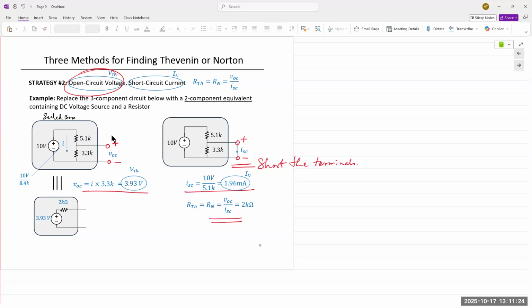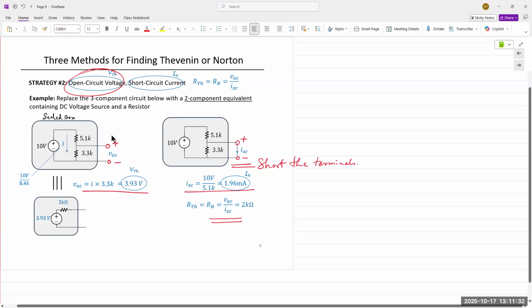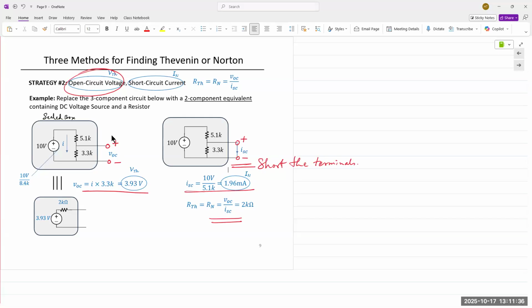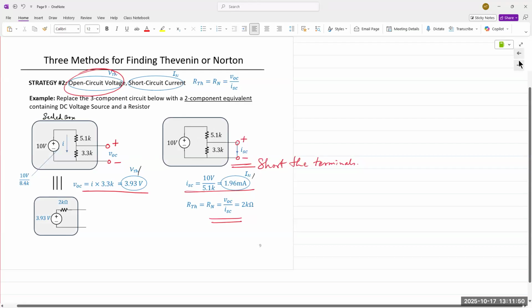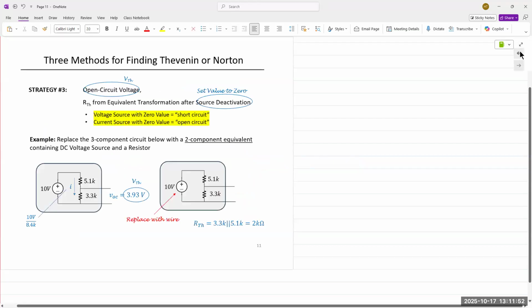That's our Thevenin voltage. If you want to find the Norton current between those same terminals, we place a short circuit wire, and then we analyze the circuit to determine the current flowing in that wire. And that would be our Norton current, IN. And then if we wish to find Req, or sorry, Thevenin resistance, then we simply find Req for that network.